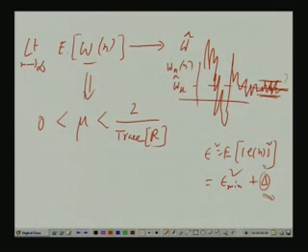Now, when you use an adaptive filter, what do you do? You see, we need En. That means there is actually a training phase in an adaptive filter, during which the desired response Dn is given to the filter, and the input Xn is given. So, you find the output Yn, then find En, and use the En in that LMS algorithm to get the next filter weight Wn plus 1, and so on in the iterative algorithm. So, during this phase Dn is available, and you train your filter, so that from Wn to Wn plus 1 to Wn plus 2 you get a better and better estimate of the filter value, so that at least in mean the filter weights converge to the optimal value.